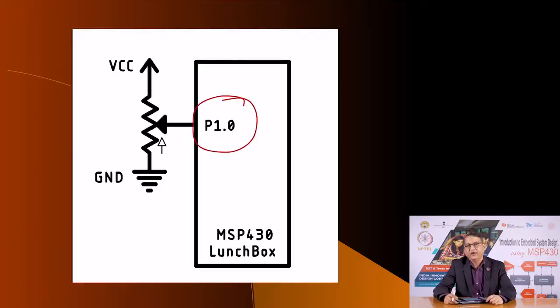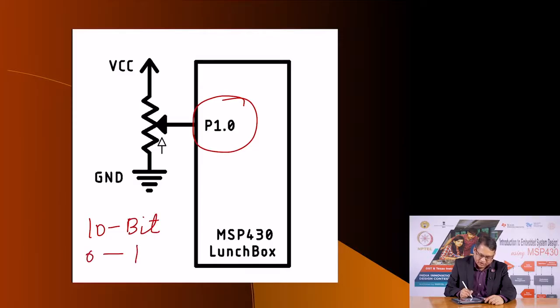As we know, we have already dealt with the ADC. The ADC on MSP430 is a 10 bit ADC and therefore, the number will range from 0 to 1023. Oftentimes, you do not need such a large variation in the number, you would like to represent this range with smaller values, and one way to do that is to take a logarithm of this number.